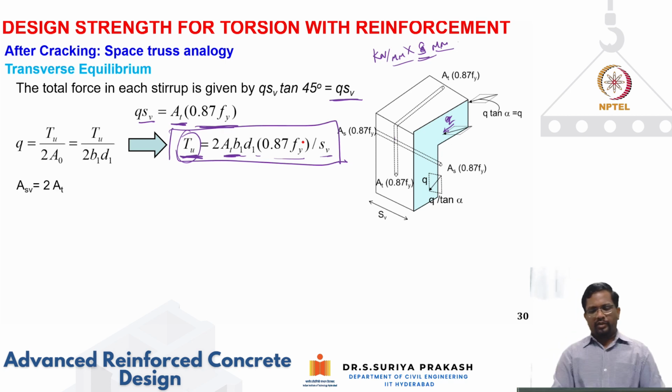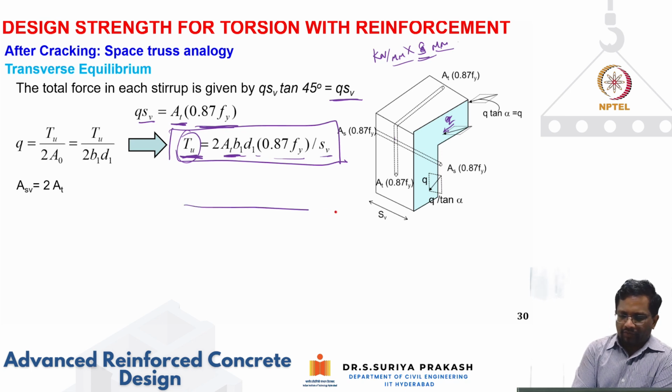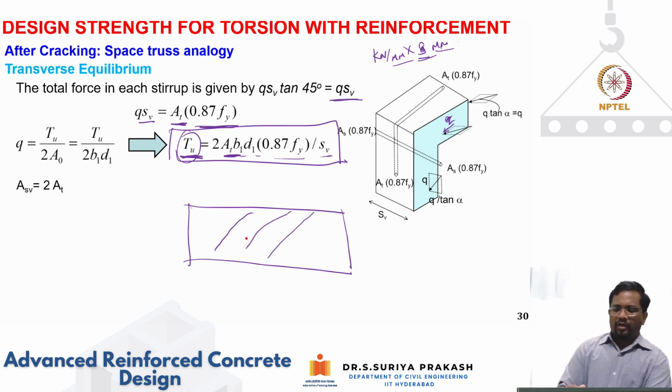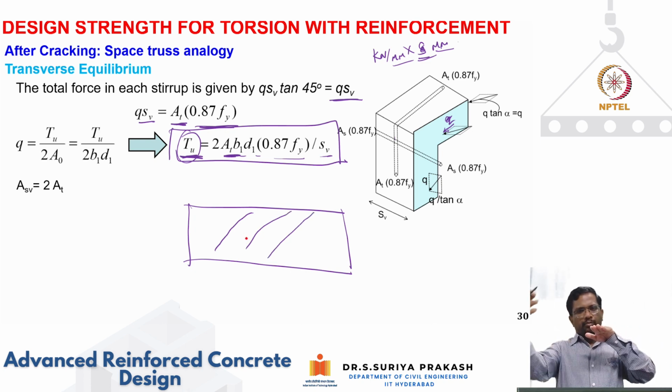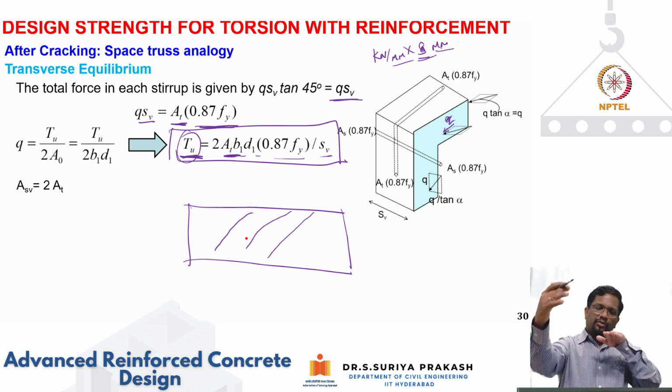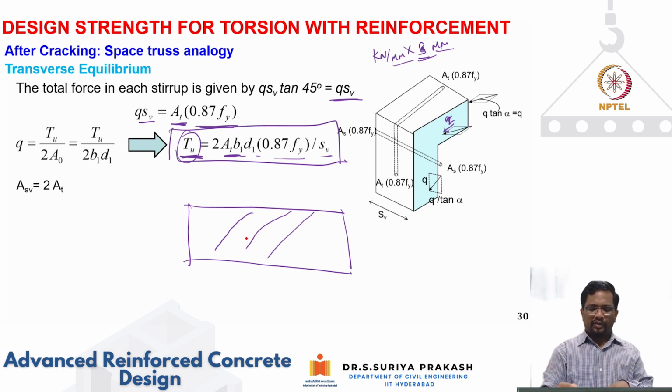And this is one thing that you have to take into account. For example, we have seen that when you have shear, these kinds of cracks are going to come. Whether you look at it from the front side or back side, the same crack will be a through crack. I will be able to see it from the front side to the back side. So the angular crack is not going to change on all the planes. It is going to be a through crack.